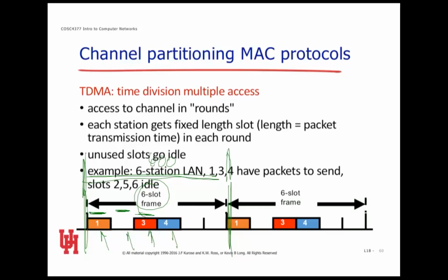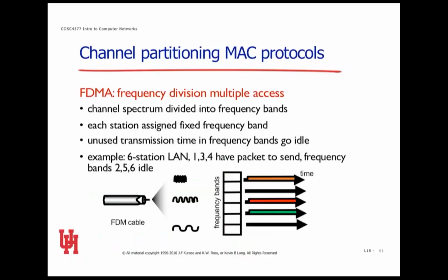That's the way voice is transmitted over a telephone network, for example, because they use constant bandwidth, and you can fit 24 of them in 64,000 bits per second because there's 8,000 samples a second. There's lots of math around it, but it's all worked out over 100 years ago at this point. So another way to do it is to channel partition.